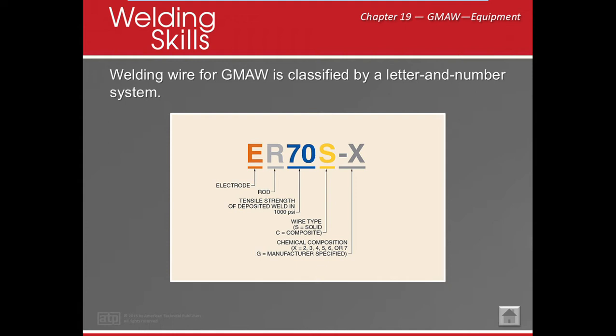So a specification has a spec in it. Imagine a big barrel as your specification. The specification is A5.18, and it is the specification for carbon steel electrodes and rods for gas shielded arc welding. It encompasses all the electrodes that are carbon steel for GMAW.